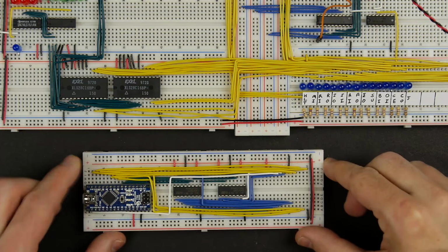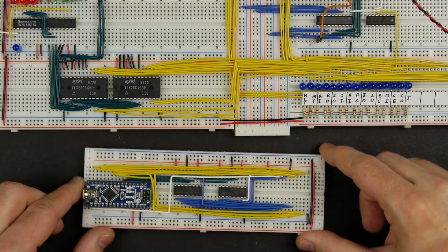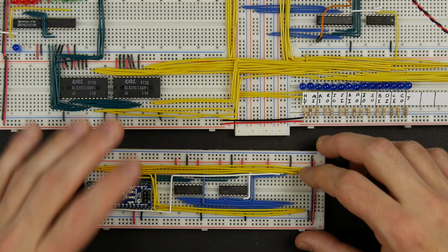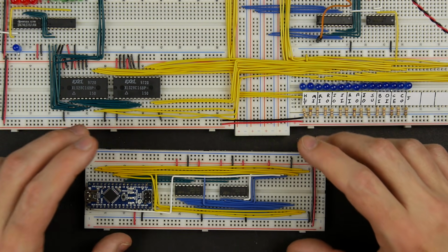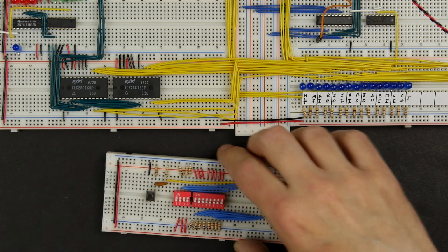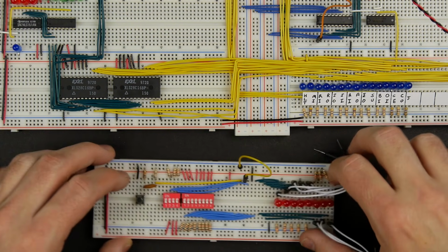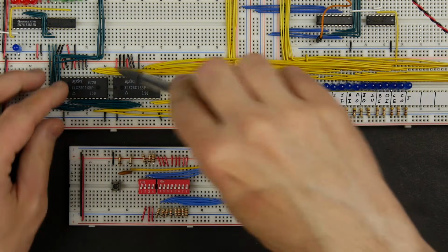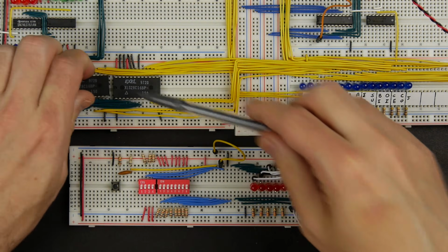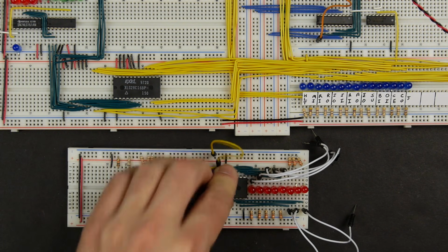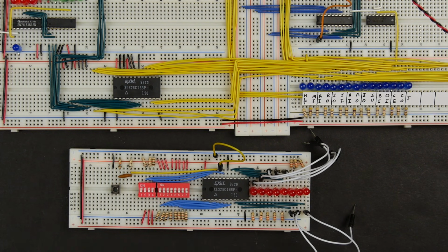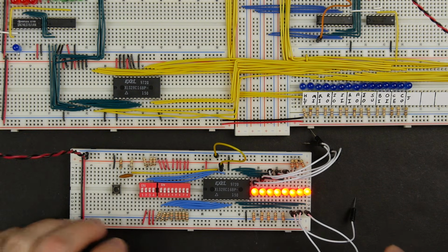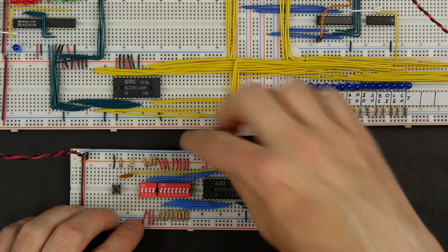Now, I built this Arduino EEPROM programmer in a previous video, and I would normally use that once the computer gets a bit more complicated and we want to program a bunch of instructions into it. But for now, I think it's going to be a little bit clearer to see what's going on if I use this manual EEPROM programmer that we also built in a previous video. So I'm going to pull out this first EEPROM and stick it in here. Make sure it's in the right place. And if we power this up, let's see, we've got all ones in there. But we want to start writing to this EEPROM.